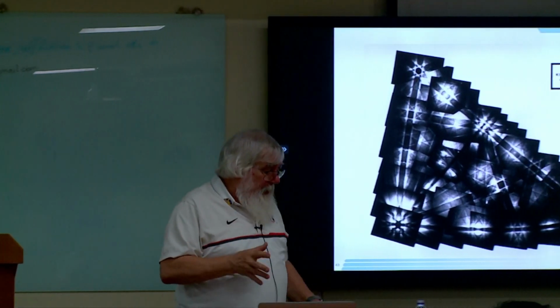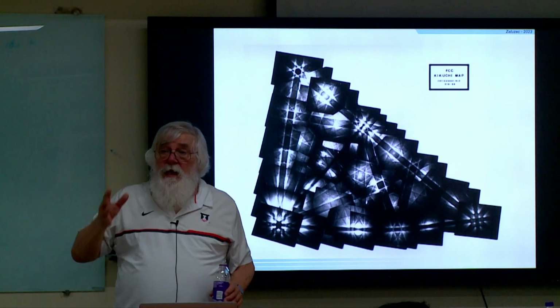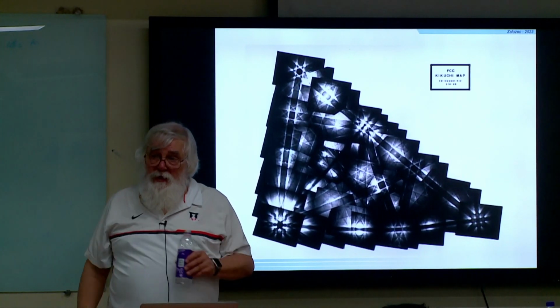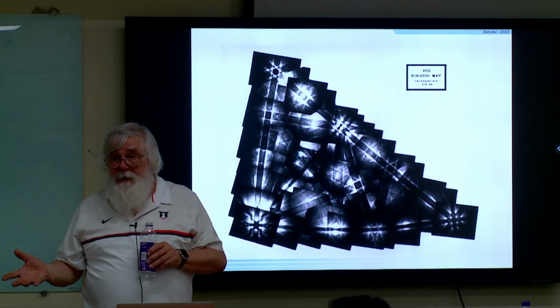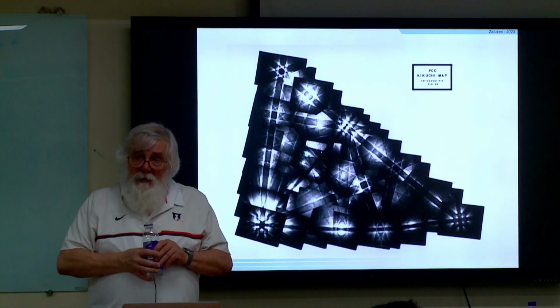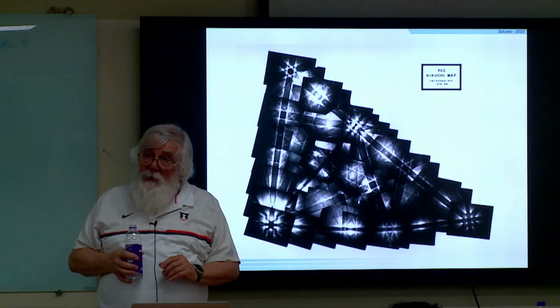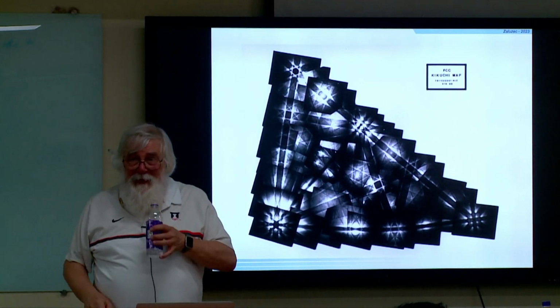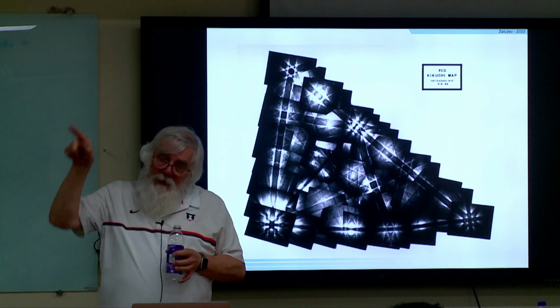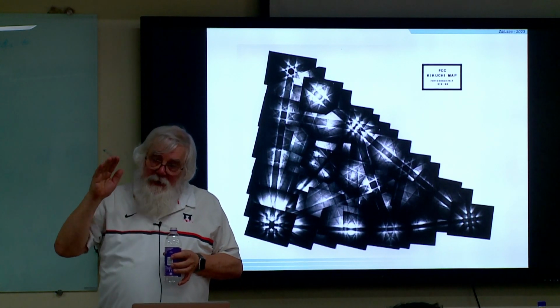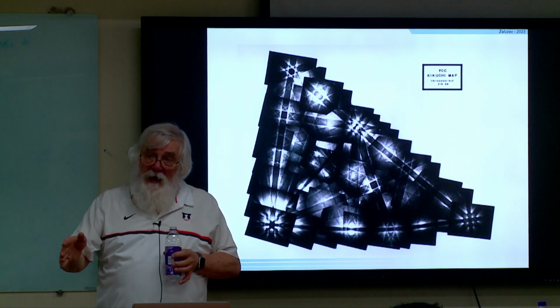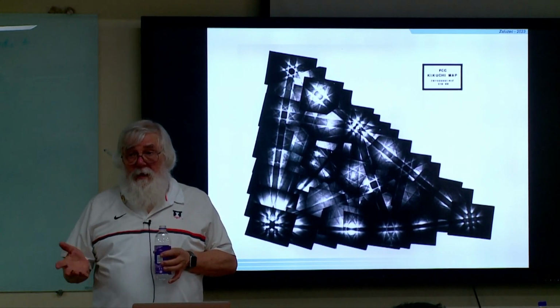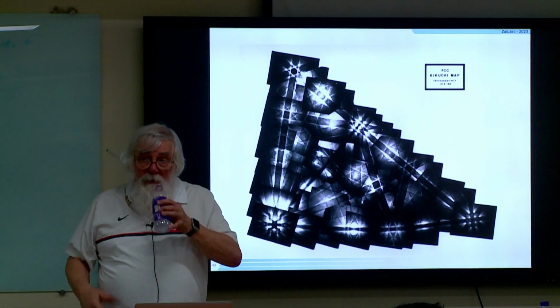Depending on the kind of question you're asking, you will need to go to different directions in reciprocal space or in crystallographic space to analyze an image. If you have a Kikuchi map in your pocket or on the wall or in your head, you can travel around reciprocal space to go to very specific directions in crystallography without spending a lot of time trying to figure out where you are.